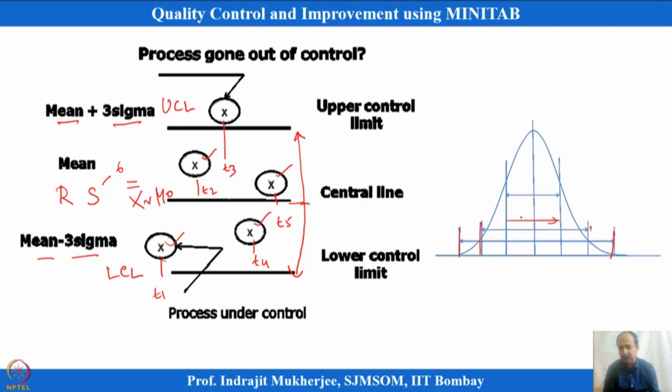This is 1 standard deviation, this is 2 standard deviation over here. So, plus or minus 2 standard deviation, and this is plus or minus 1 standard deviation, and this is ultimately 3 standard deviation, 3s over here, assuming that s is a perfect estimation of sigma. Okay. So, if this is the limit line, but one observation we see over here is at T3, let us say x3, this has gone outside the limit lines.